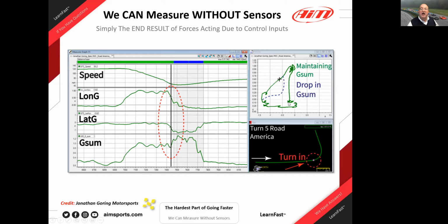Those people that do one axis well are a dime a dozen. So the people that brake well, go bang, pin the brakes, get the nose to kiss the pavement, that's easy to do. If they release the brakes and coast and roll without really taxing the tires, there's this depression, this cutout, which is this blue dotted line, to maximum lateral acceleration, which is over here. Now this car is braking at 1G and got a maximum of over 1.25.